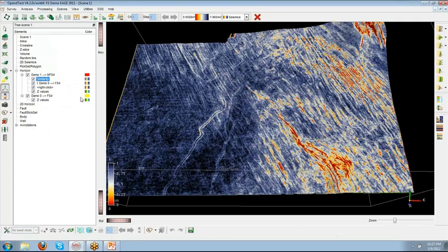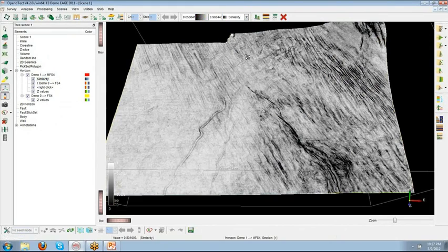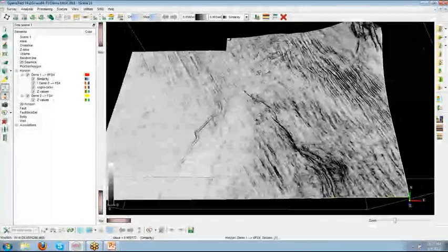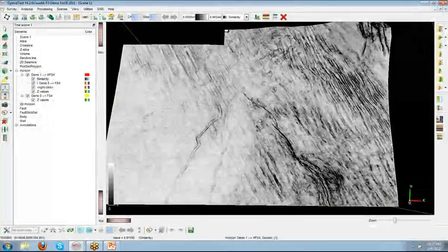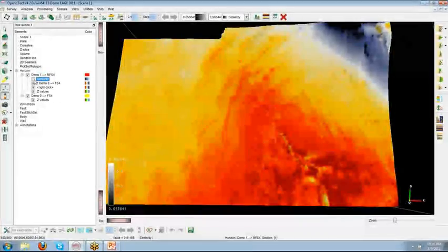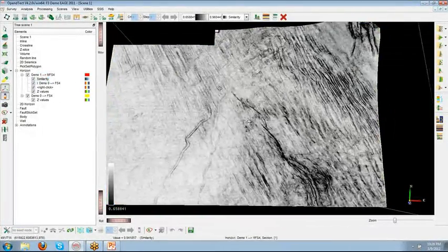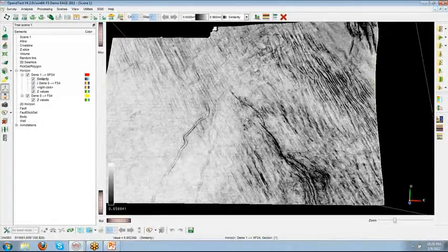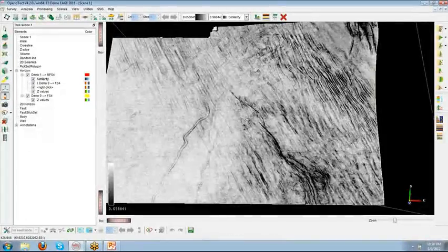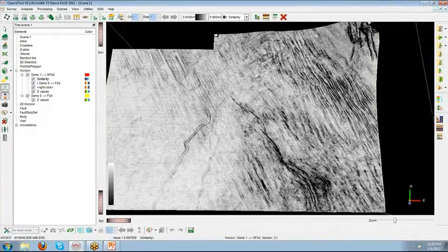Similarity was computed beforehand and has now been restored as a surface data. And what we can see, and that we could already see a bit before on the isopach map, is that this dataset is split in two with a major fault offsetting the data that I'm highlighting here with my mouse pointer.